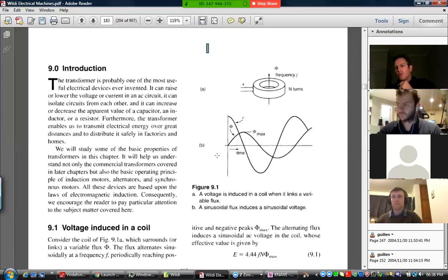On a sine wave, the steepest rate of change is at the crossing, and the smallest rate of change falls to zero as it flattens off before it goes down again. So where there's no change, we've got a horizontal tangent and we get zero EMF induced in the coil. And when there's a steep change in flux with respect to time, then we get a high peak. Or if the flux is changing negatively over here, we get the low peak.